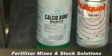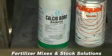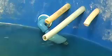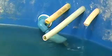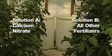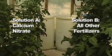Fertilizer mixes are usually prepared beforehand as stock solutions. These concentrated solutions are then fed into the irrigation system and sent to the plants. Usually there are 2 stock solutions prepared. This is to prevent the mixing of incompatible fertilizers that would lead to the precipitation of insoluble salts. Solution A contains calcium nitrate. Solution B contains all other fertilizers.